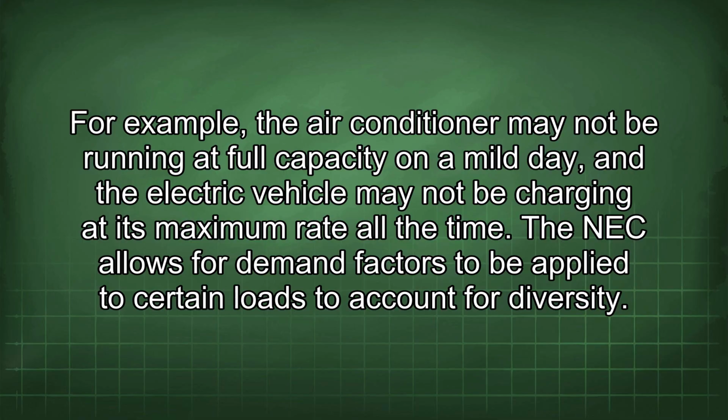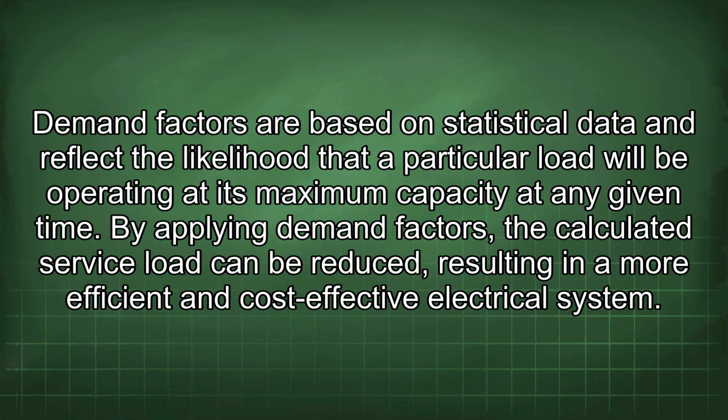The NEC allows for demand factors to be applied to certain loads to account for diversity. Demand factors are based on statistical data and reflect the likelihood that a particular load will be operating at its maximum capacity at any given time. By applying demand factors, the calculated service load can be reduced, resulting in a more efficient and cost-effective electrical system.